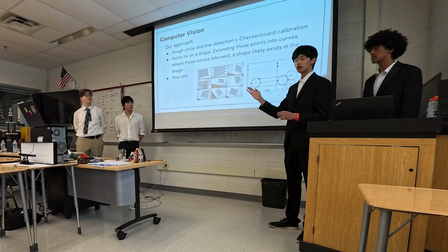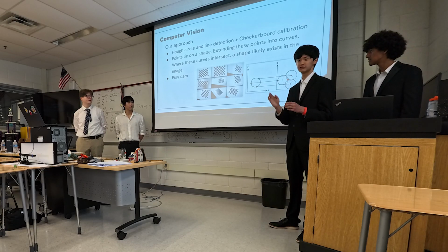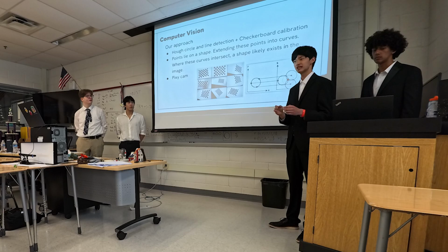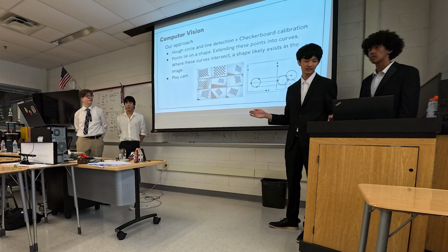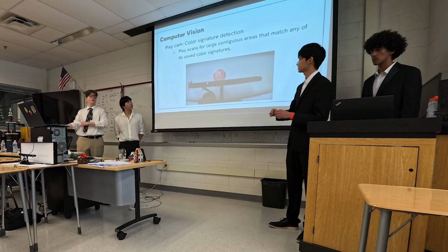Overall, while it did work, we found it to be quite difficult to use because we would have to drape a curtain to the background of the actual system, as well as the fact that it would also detect irrelevant lines that weren't a part of the actual system. So instead, what we chose to use was a PixieCam, which uses color signature detection.